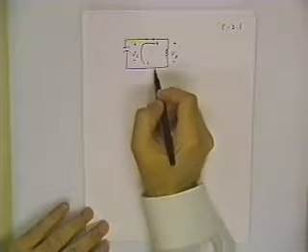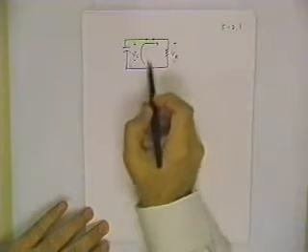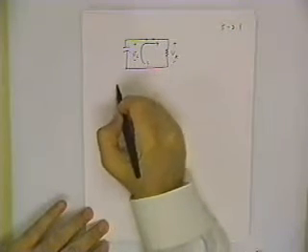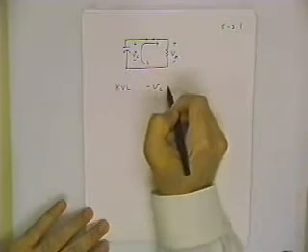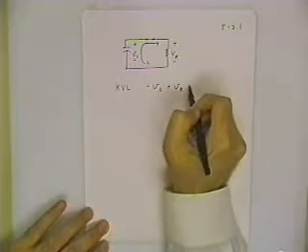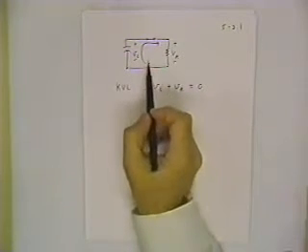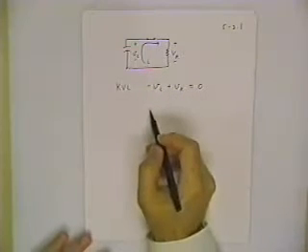Now let's do the Kirchhoff law first. If we start at, say, this node and go around clockwise, I bump into a minus sign on the capacitor and a positive sign on the resistor. So I'd write the Kirchhoff voltage law: minus VC plus VR equals 0. But now what I want is an equation for I. And so I need to substitute my models.